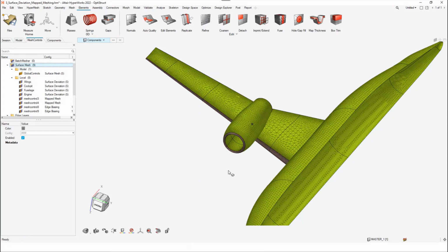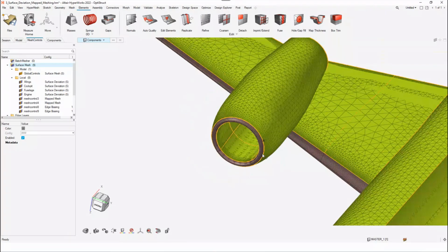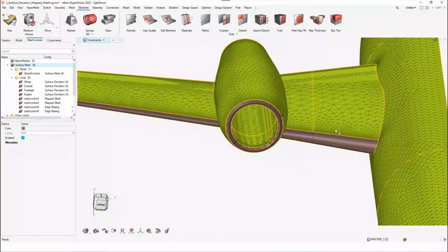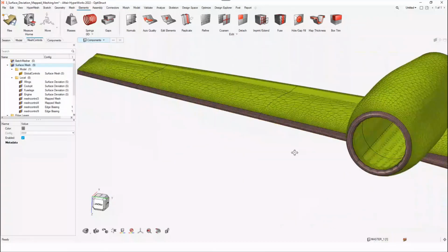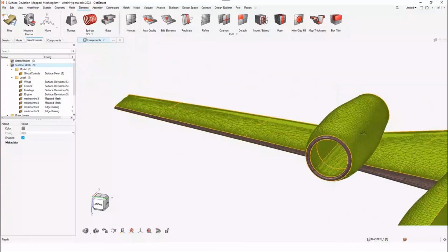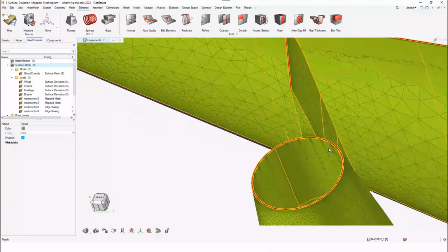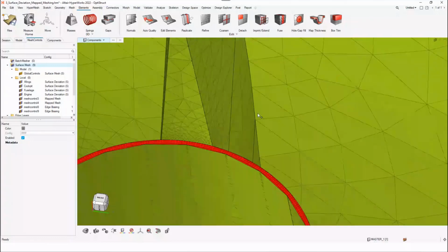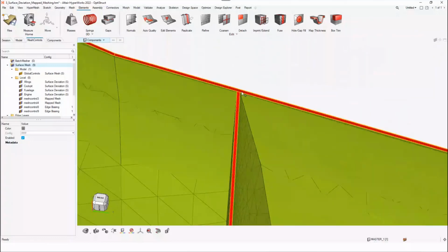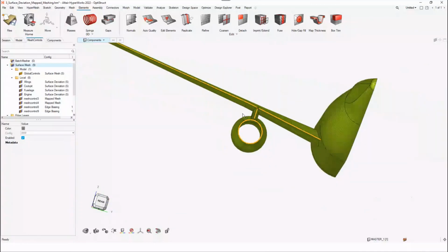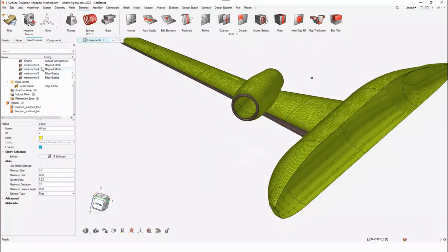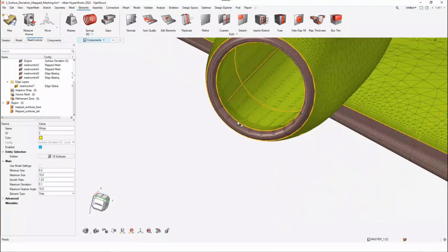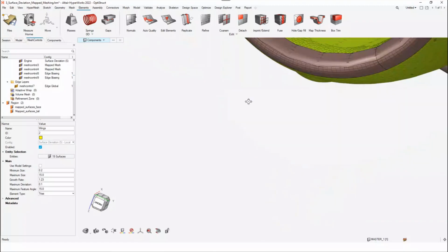Okay. Now if you see the front facing surfaces I had defined with the map mesh, you would get all the chord elements here. Similarly, you would get tail faces as well, the number of layers and chord meshes. So these are the ones. The rest will all be meshed according to your other mesh controls defined. So basically the edge deviation I have defined is from this.